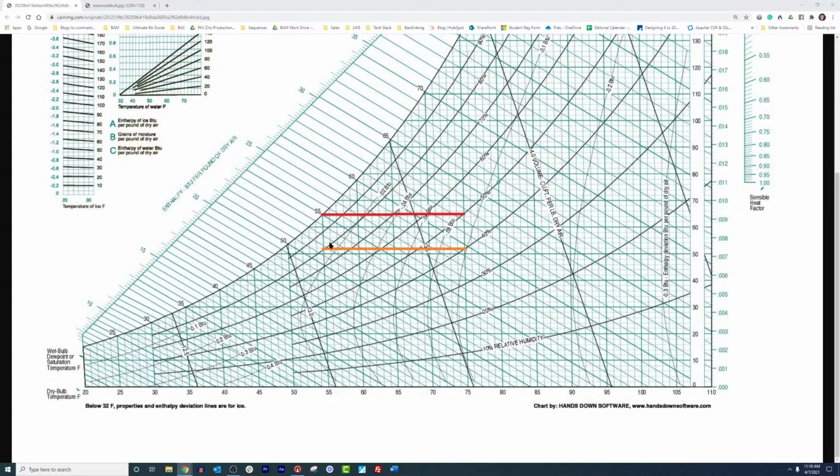You can have a cutoff when your space, because if I remember correctly, it's 60% relative humidity and greater within the space is likely to get mold, and then 70% or greater is like, yeah, you're going to get mold. So that's what I would look at. Hopefully that helps. What other questions can I answer for you all?